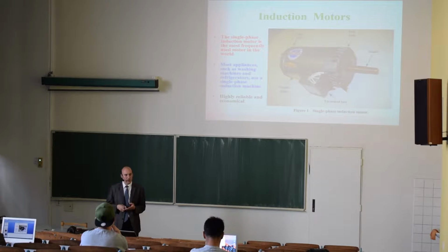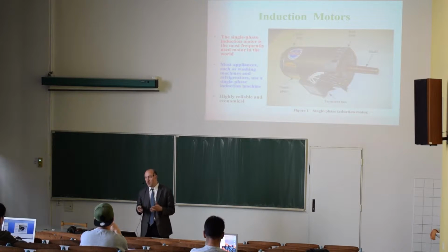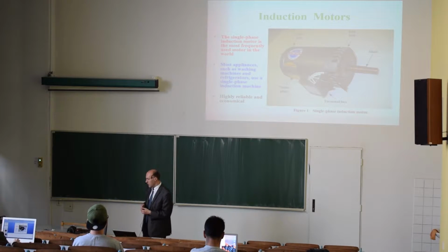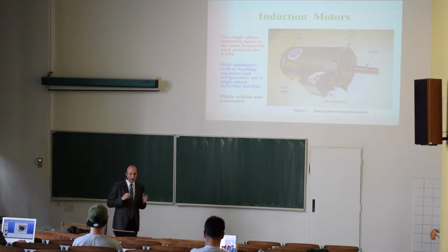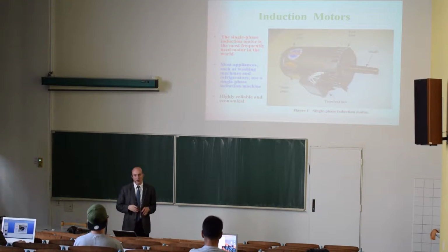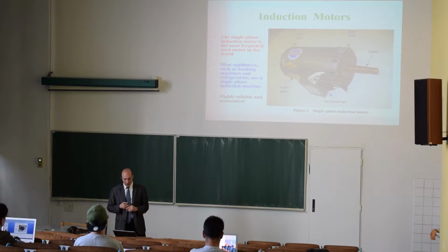If you have, for example, handheld tools like a drill, you need it to be light, and an induction motor of this kind would be very heavy. Although it would be quite good in terms of maintenance, if you had a drill that weighs 10 kilograms, then it would not be a good drill. So standard induction motors are used everywhere where we don't care that much about the weight.